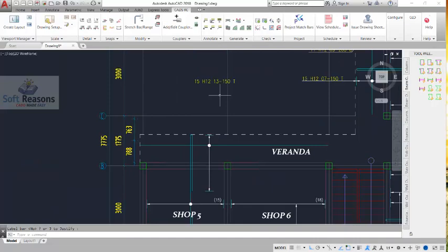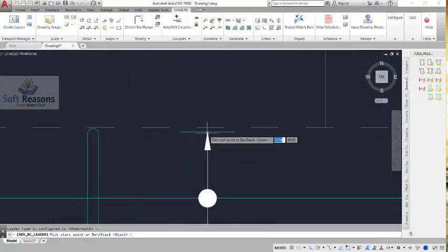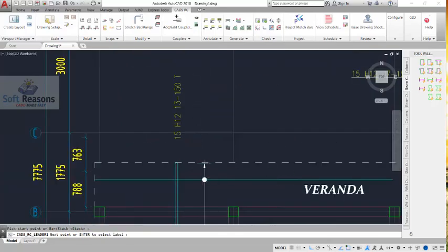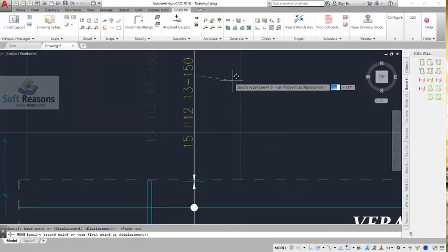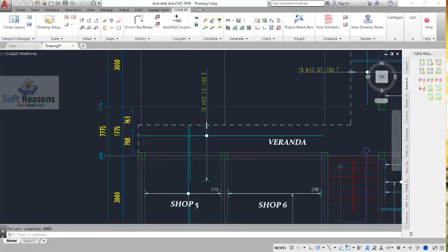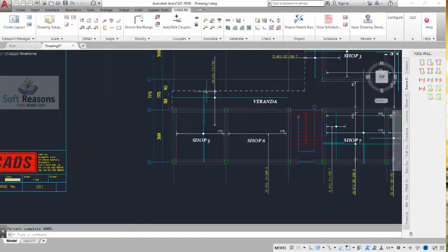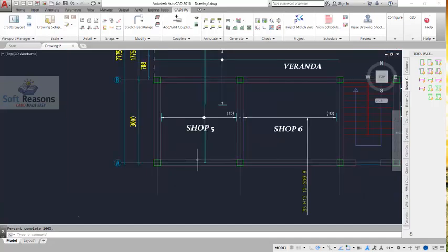Okay, place the bar right here, rotate it upward just like this, and then move this closely. Use the leader line to call it out, just like this, to this point. Move this, and then activate your polar, so you can move it in any direction. So this is a top bar for this cantilever, successfully. All right, we may progress.